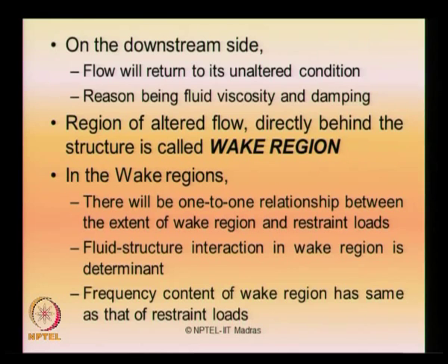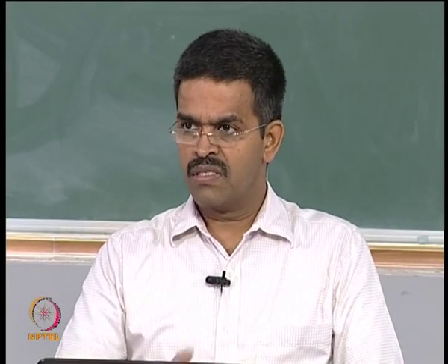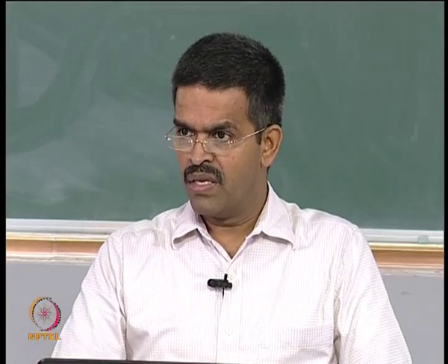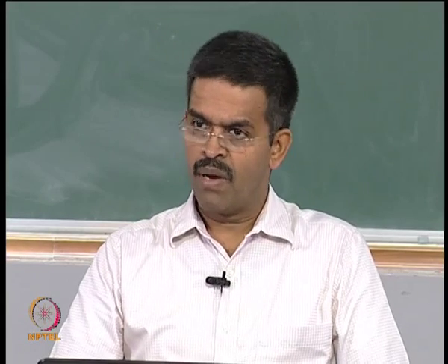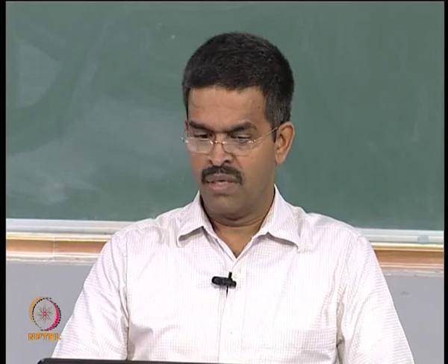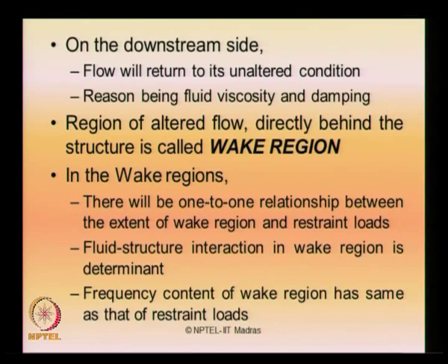So wake region is simply a region of altered flow, or a disturbance created because of the presence of the member. Now how long this disturbance will be created, the extent of that region, is governed by the restraints offered by the structure, either because of its compliancy or because of its boundary condition with respect to the seabed, maybe bottom supported, maybe compliant, maybe floating, etc. Now the fluid structure interaction in the wake region is interestingly determinate; it can be easily computed, and you can have a closed form solution for the interaction of the fluid with the structure essentially in the wake region.